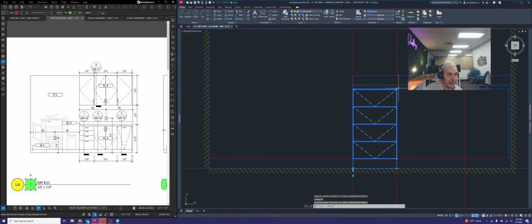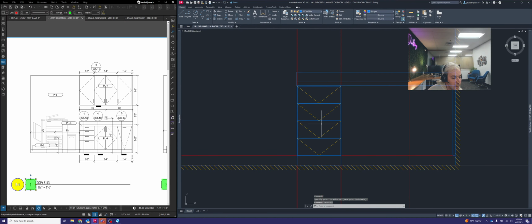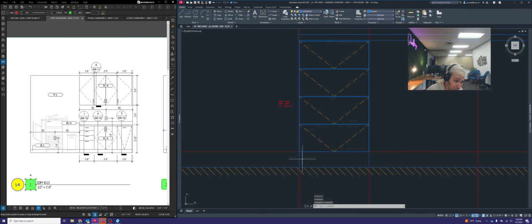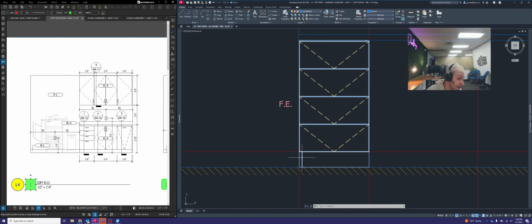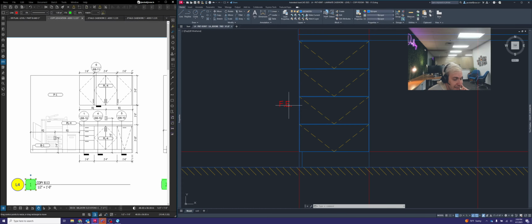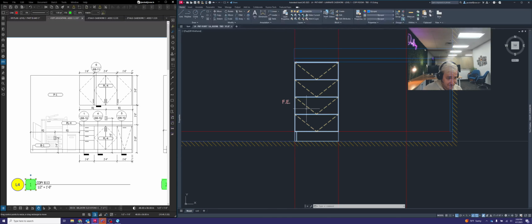countertop, just like that. All right, before I call this done, let's go ahead and turn on the finished end. Get the second icon down. On the left-hand side, we're going to have a finished end over there. So that's going to add that little piece of base trim, or actually the base trim will stop at the sidewall of the cabinet. And what you're seeing there is a sidewall extending down into the base trim right there, which is what that extra line is. It also adds on the finished end label right there.